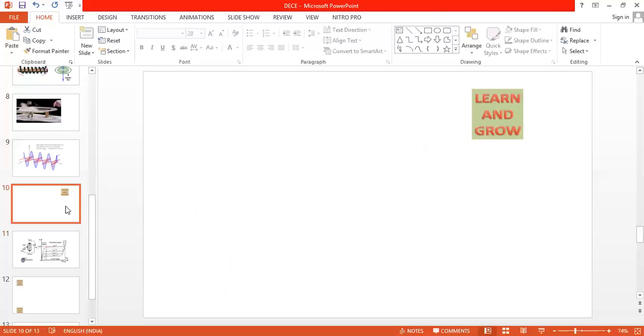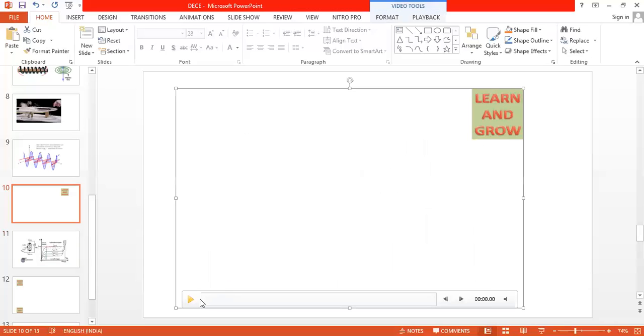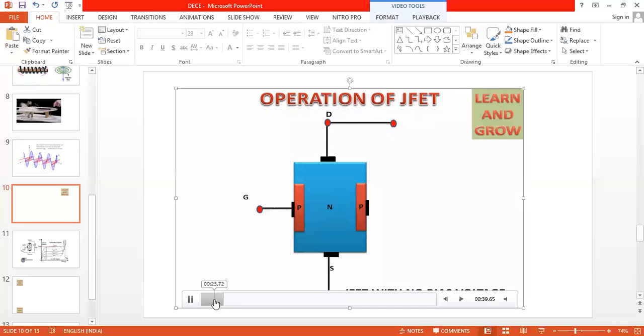So we'll see once again, what exactly is the FET? Same points you can write. A FET practically contains n-channel semiconducting material on which at both ends two p-type materials are diffused. When p-type and n-type are diffused together, a depletion region will be created. The depletion region will be maximum at the drain terminal and minimum at the source terminal, because the drain is having high resistance, because the positive terminal is connected here.